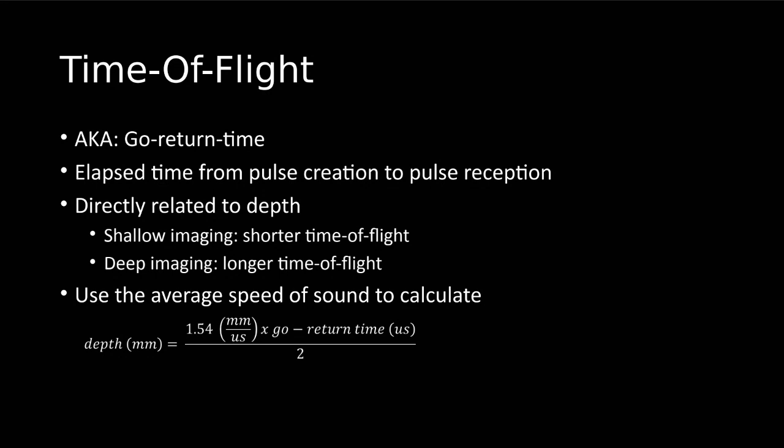How long is it taking for that pulse that was created in our transducer to get where it needs to go and then to also come back to us? So we're looking at that total travel time. So time of flight, it's exactly like if you're going on vacation somewhere, right? You want to know how long is it going to take you to get there, but then we also want to know how long is it going to take you to get back home. Usually it should always be the same amount of time to get there as it takes you to come back. So we're just calculating that.